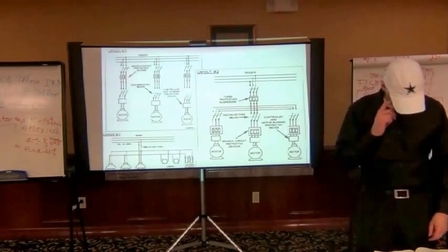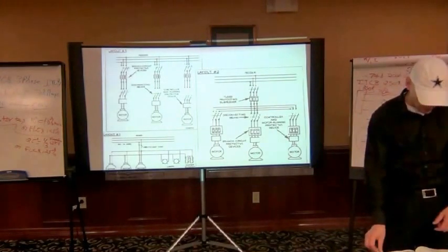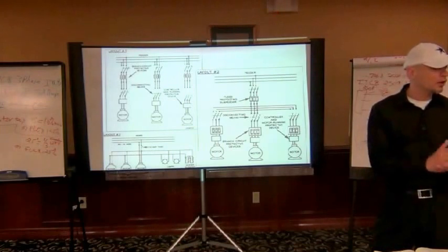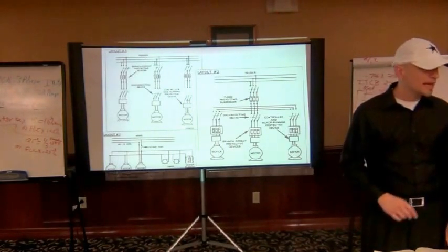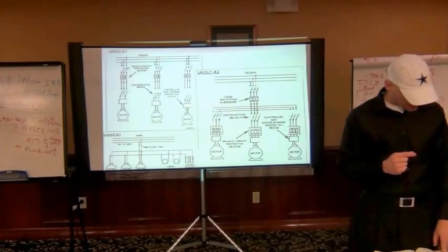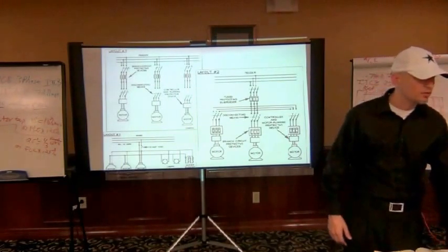You can just write page 337, 338 for you guys, and for y'all, you'll also have 339. And also for the masters, just in case you run across it, at the bottom of page 338, the table for your 3-phase under 250, if you have a 90% power factor or an 80% power factor, you take the table value.